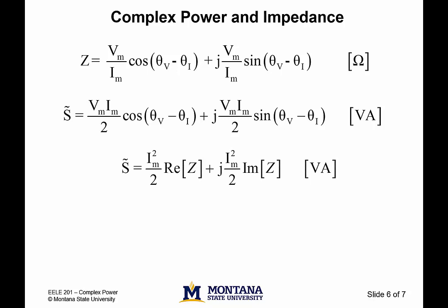Really, all we're doing here is using Ohm's law in the frequency domain to replace Vm with Im times the real part of the impedance and then the imaginary part of the impedance. Here is just another way of identifying average power with the real part of the impedance and reactive power with the imaginary part of the impedance. We can't introduce complex power without thinking about the complex plane. We do that next.